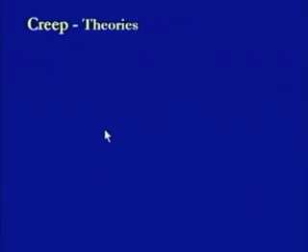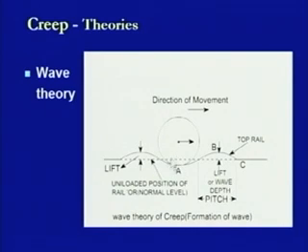Now, this is the condition which is happening because of a single wheel. This single wheel is being placed here, and whatever load is being transferred, this load is transferred at this position. This is the normal rail level at this point. This dotted line is showing the normal level of the rail at which this wheel was placed. Now, because of the loading condition, there is this much deflection being caused in the rail section.